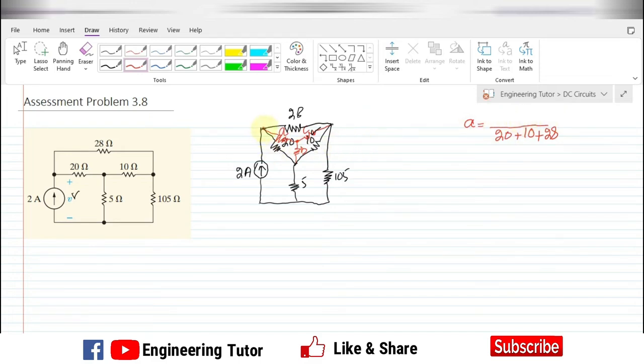So at junction A, where resistor A is connected, we have two other resistors in the delta configuration, which are 20 and 28. Solving it here, 560 divided by the sum, which is 58, will give me 9.66 ohm. Okay, I have calculated it earlier on.